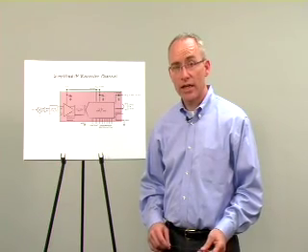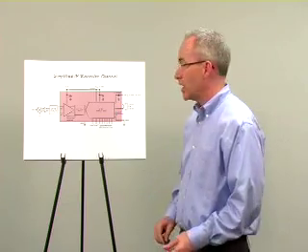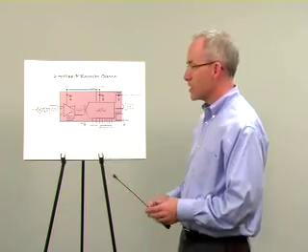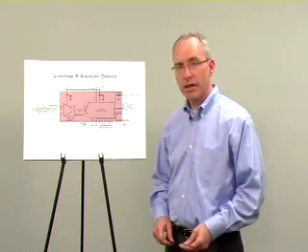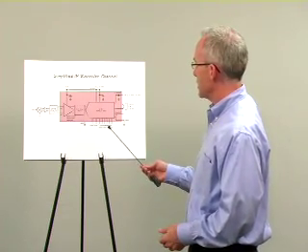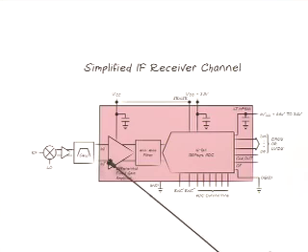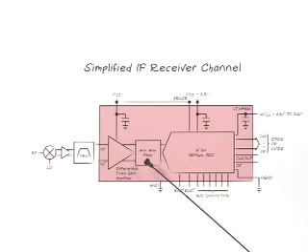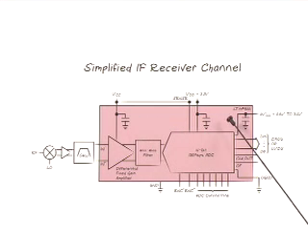The simple way is to find an ADC with resistive inputs and none of the switching transients, yet all of the speed and performance of the pipeline converters. The LTM9001 gives you exactly that. It includes the amplifier, the anti-aliasing filter, and it also happens to include the reference and bypass caps, since the layout of these caps also affects performance.